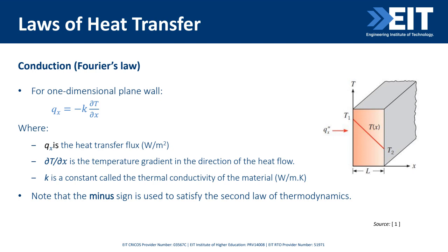Now, when we talk about heat transfer, we cannot neglect the laws of heat transfer or fundamental equations. We just need to not remember, but understand three important equations, each equation for one mode of heat transfer. For conduction, we have Fourier's law, which talks about how much heat is transferred from a higher temperature to a lower temperature in a particular direction. How much energy is transferred per unit time is known as heat transfer rate, and if we divide that by the surface area, then we get the heat transfer flux.